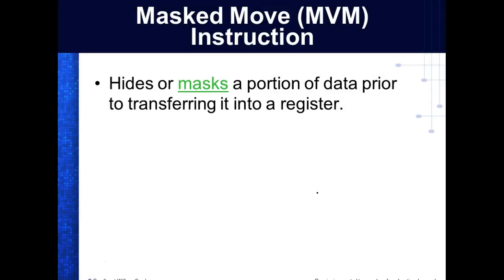Okay, mask. Everybody understand what a mask is? When we mask stuff, we cover stuff up, right? An OR mask will mask it with a 1. So it doesn't make any difference what the other operand is. If I have a 1 in the OR mask, I will always get a 1 in the answer.